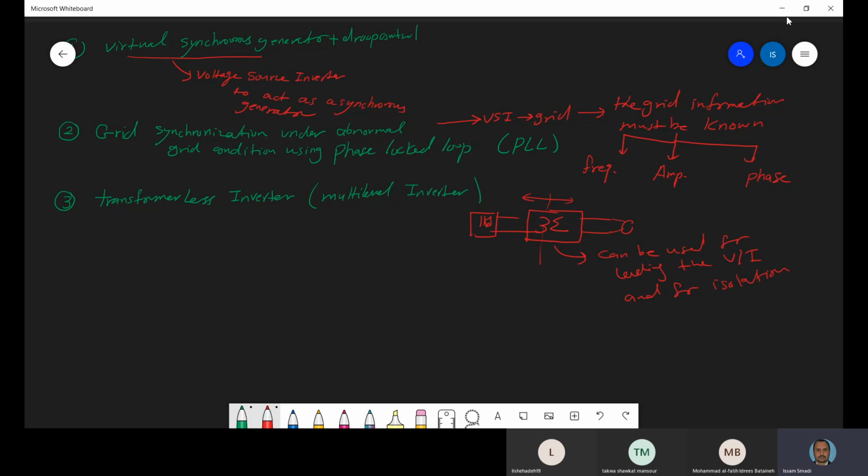And if we have here any DC component, it will never appear here, correct? Why? Because here we have a transformer, and you know the transformer only will transfer what? Alternating signal, not a DC signal, correct? So the alternating signal will be transformed, either leveled up in voltage or current according to the turn ratio of the transformer, but the DC